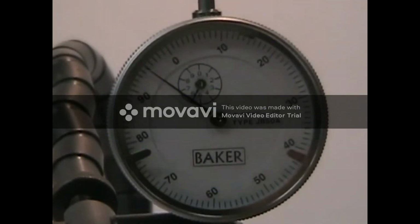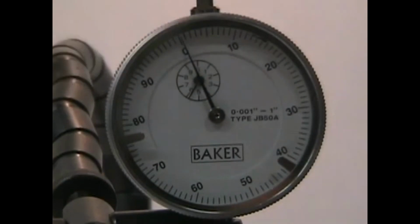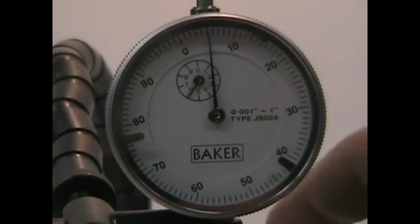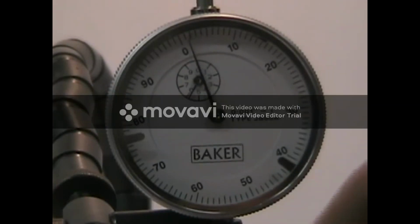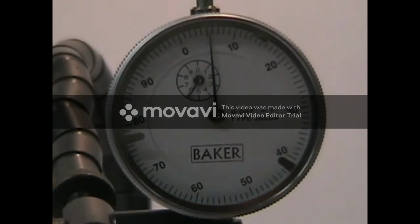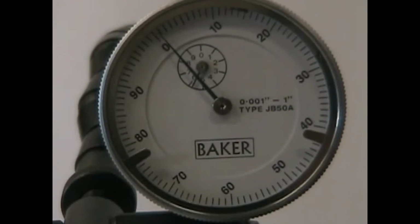Stop when the needle moves to the maximum position to the left and rotate the bezel so the zero aligns with the pointer. Continue rotating the part until the pointer gets to the maximum position on the right. The total movement between the left and right measurements is how much runout or distortion the part has. In this example, the needle starts at 0 and moves 6/1000ths to the right. The total runout of this part is 6/1000ths of an inch.